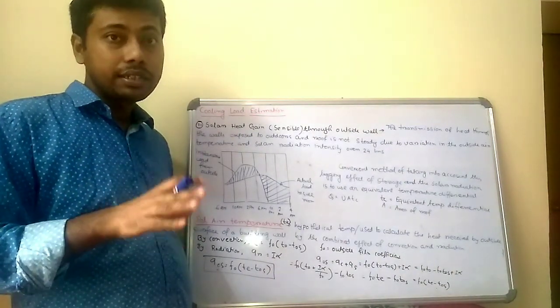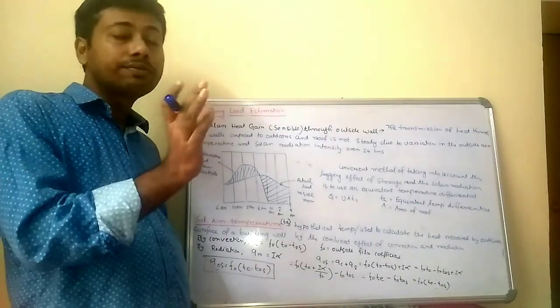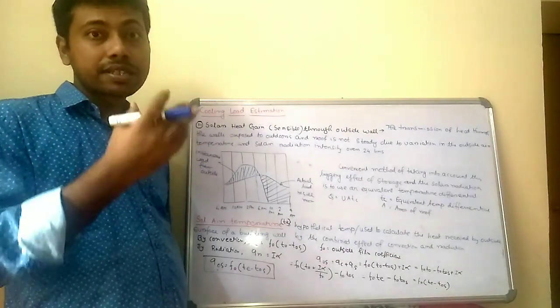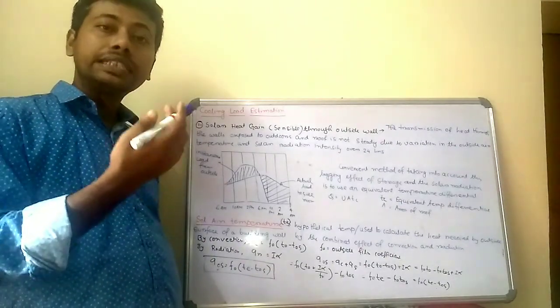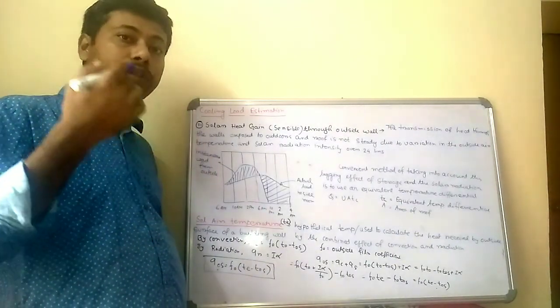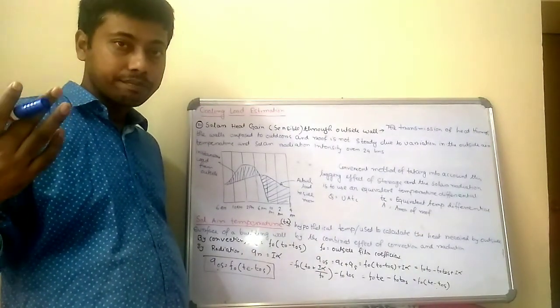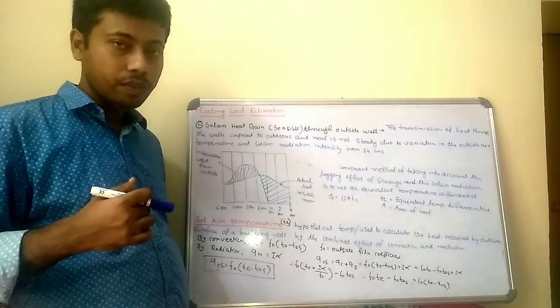They will release the heat, which is actually the amount of heat absorbed over the whole day from 6 a.m. to around 6 p.m. They will release it after 6 p.m. So that's why the outside temperature beyond 6 p.m. is less compared to the room.